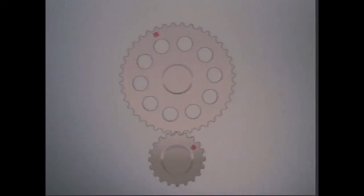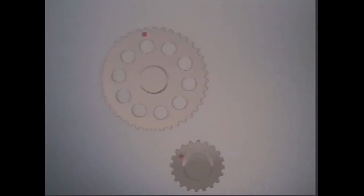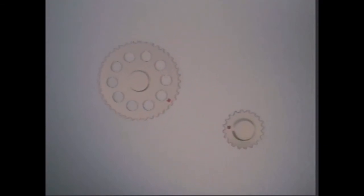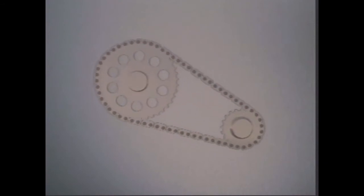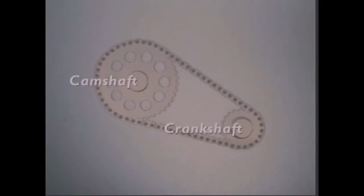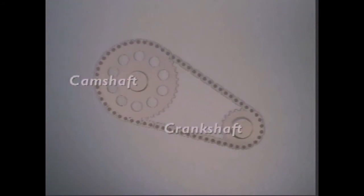These gears turn in opposite directions, and the one with fewer teeth rotates faster. Now let them be separated but linked by a chain. They turn in the same direction, at the same speeds as when they were meshed. If the smaller gear is attached to the crankshaft and the other to the camshaft, how fast will the camshaft turn compared with the crankshaft? It will turn at half the speed, just what the system needs. Everything happens at the right time.